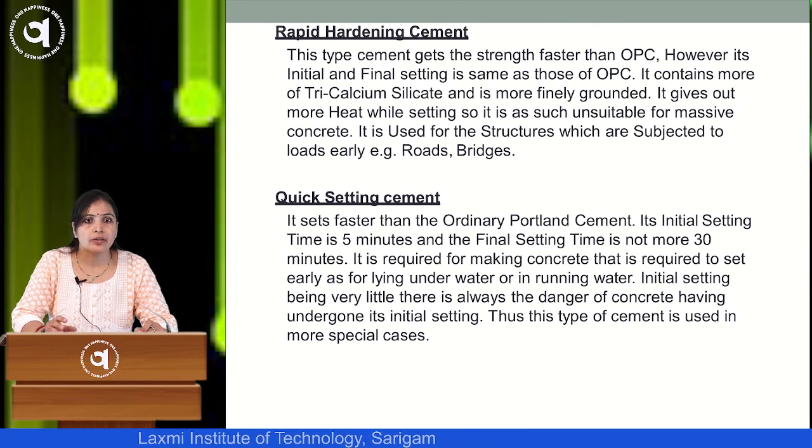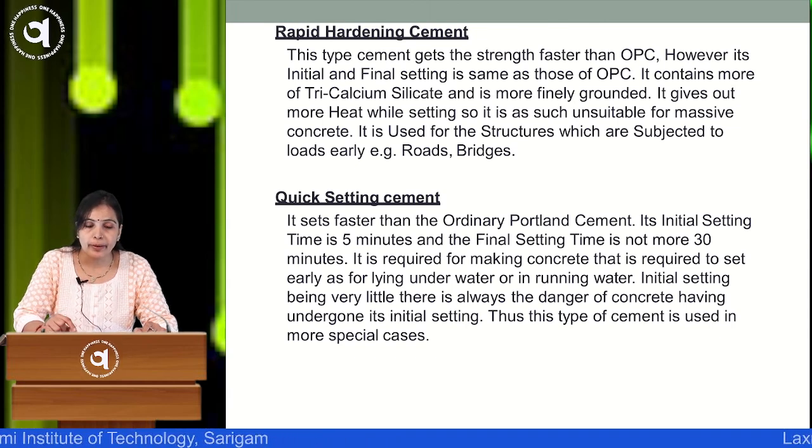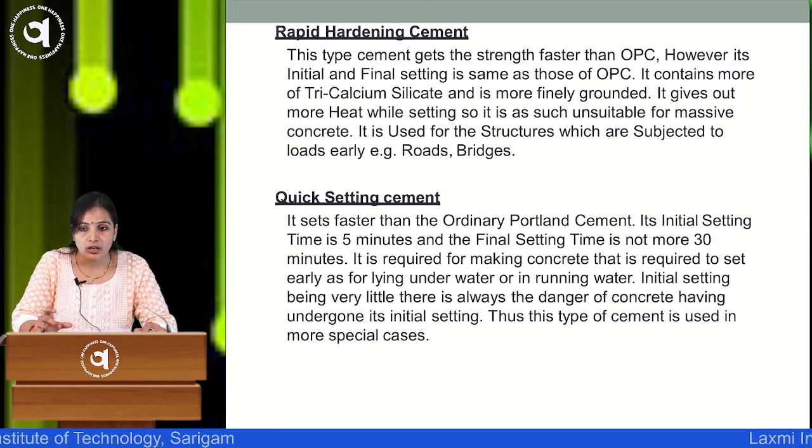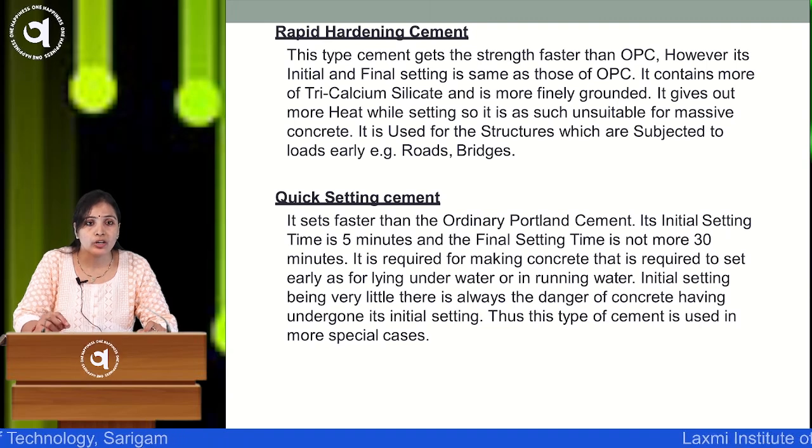Since the initial setting time is very little, there is always a danger of the concrete having undergone initial setting. Thus, this type of cement is used in special cases. So, one demerit is also here: when the initial setting is only 5 minutes, then we have to be keen observers and use it under special cases only. If we want to construct any structure in running water, then we can prefer this cement.